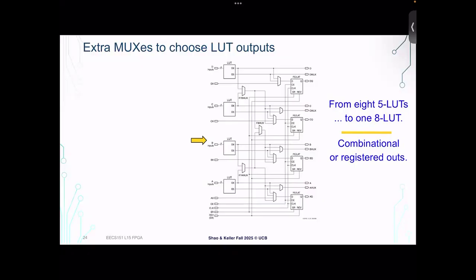Okay, yes, question? Are the 6, 7, and 8 actually physically hardwired? Yeah, so everything I'm showing here is physically hardwired. All of these muxes and lookup tables are physically what has been taped out in the FPGA that's sitting on your bench. And then the programmability comes from setting all of the values in the lookup tables, setting all of the select bits for the muxes. That's going to set it to the particular function that you've defined in your RTL.